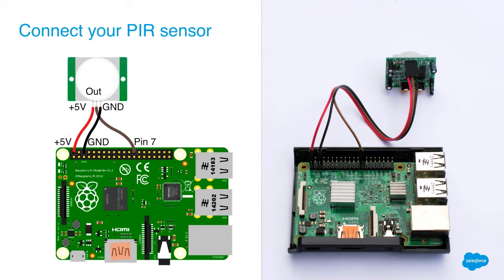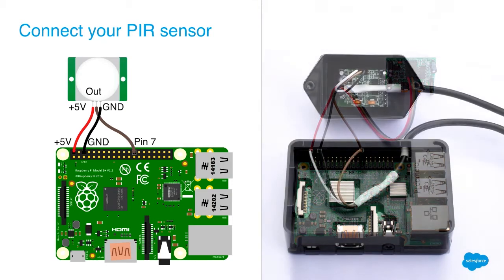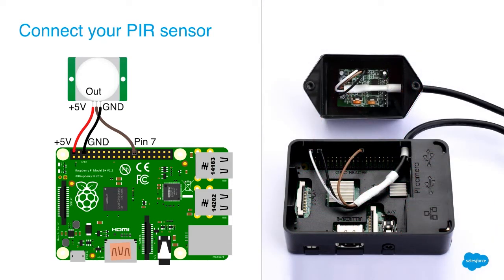When we built our Pi 3, we've got an image of it here, and if you watch closely, you'll see that the connections have not changed. We did change the packaging, because when we built our Pi 3, we were getting false positives from the sensor. We did a little bit of research on it, and we found out that there is an interaction happening between the circuit boards when they were in close proximity. So the only change we did have to make was to get some distance between them. We put a 1-meter cable on the infrared sensor. It fixed the problem. Everything else is identical. Libraries, script code, everything else is the same.